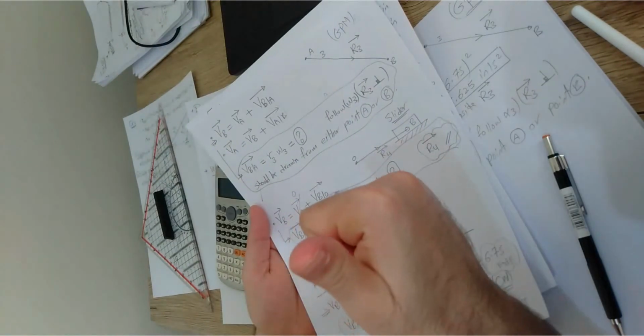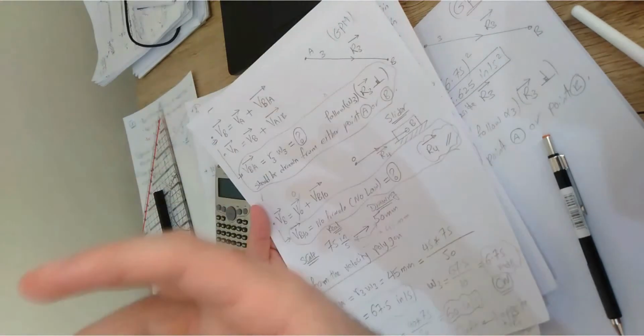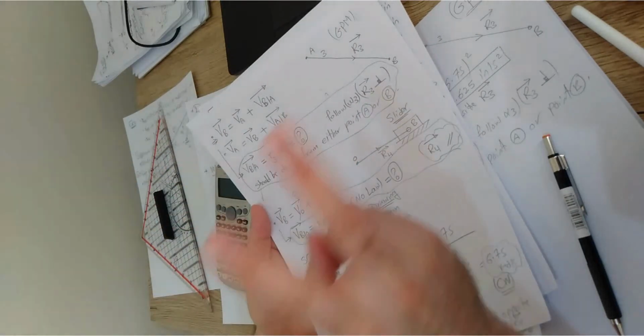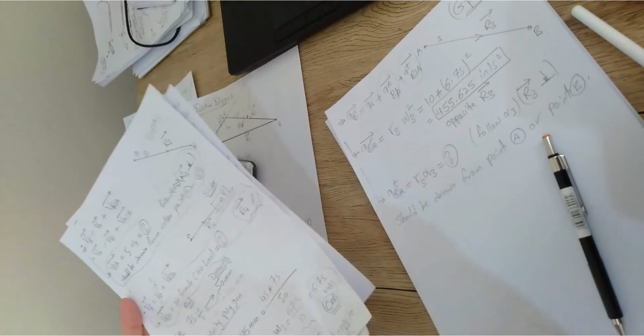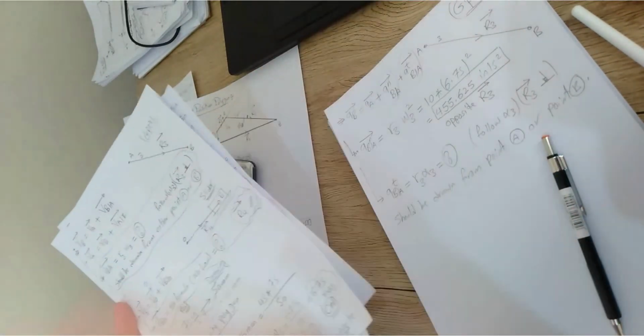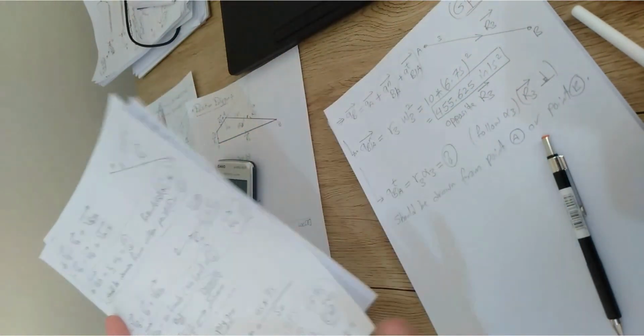The acceleration equation will have 2 relative acceleration components: one normal, the second tangential. All the time, the normal is R omega squared, all the time it is opposite to the R of the same length that you're considering, and it will be known.